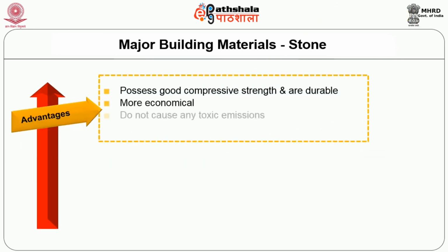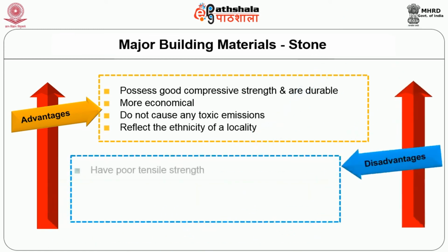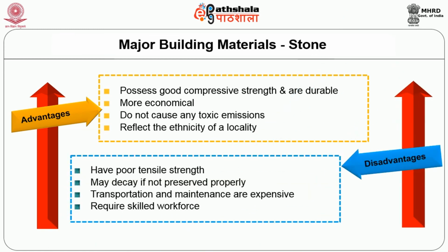Now, let us see some of the advantages of stone as a building material. They possess good compressive strength and are durable, they are more economical, they do not cause any toxic emissions, and they reflect the ethnicity of a locality. The disadvantages are they have poor tensile strength, may decay if not preserved properly, transportation and maintenance are expensive, and they require skilled workforce.